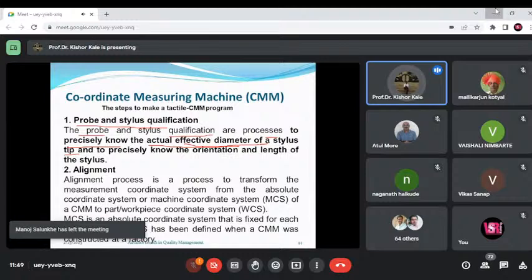CMM enables tracking the correspondence between the nominal and manufactured surface for tolerance verification, that is, traceable geometry is possible. To respond to the market quickly, it has become inevitable to use 3D scanners to scan an object with multiple unorganized points as an input in online or offline mode. This shows the time required is very less in the case of scanners. But an important drawback of non-contact is that traceable geometry is not available.